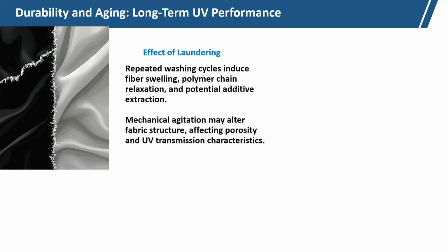After a long time we must go for laundering, and repeated washing cycles are required. Repeated washing cycles induce fiber swelling and polymer chain relaxation, and potential additives added on the fabric surface, different types of finishing and coating, may get extracted.